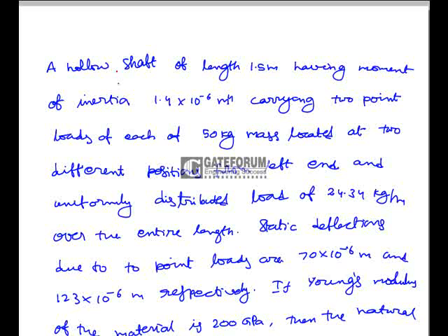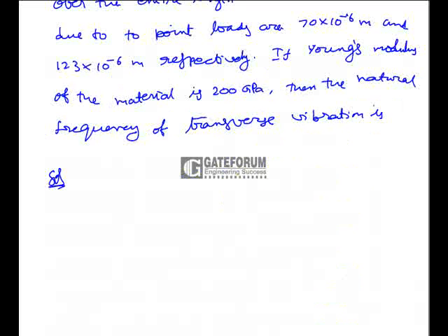Static deflection due to the point loads are 70 into 10 power minus 6 meters and 123 into 10 power minus 6 meters respectively. If Young's modulus of the material is 200 gigapascal, then the natural frequency of transverse vibration is. Here for this case, natural frequency of transverse vibration is given by 0.4985 by